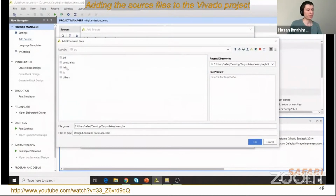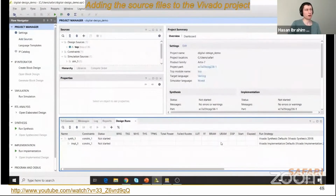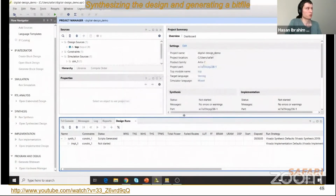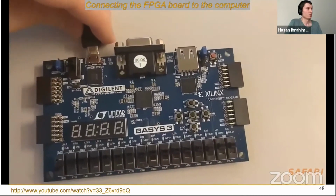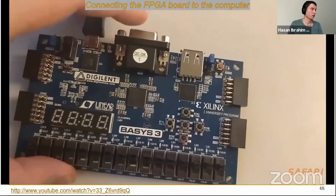So specifically here, we will connect the wires coming out from the FPGA chip to the USB, because we will be connecting our keyboard to the FPGA using the USB interface, as you will see shortly. But here we just simply generate the bit stream because we are done with the design. We added all the source files, but obviously in the lab sessions you will need to write those. You'll basically have to design your module yourself.